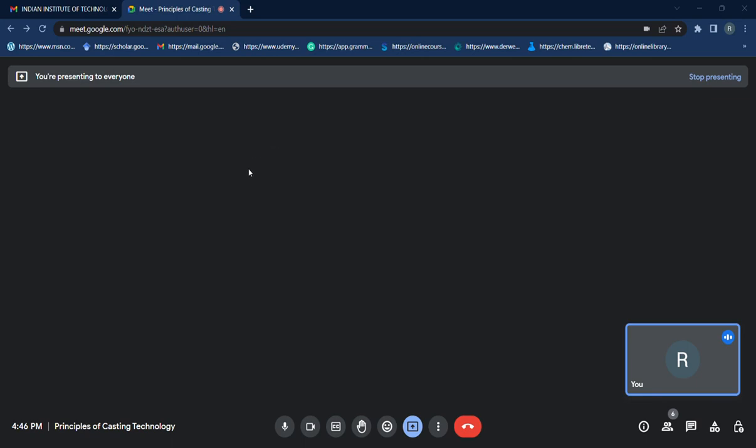Your x is the ratio of the a by v of the casting and your riser. The area of the casting is 1750, calculated as 2 into LB plus BH plus HL. The volume of the casting will be 3125, as 25 by 25 by 5, since it is a cube.